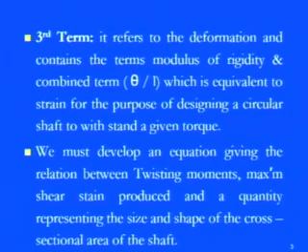So generally, if you remember the previous case, we found that AB was the length in the circular bar. Whenever there is no loading condition, all those layers are well set up within this circular bar. But as we apply the torque, B was shifted to B dash, and that shifting was at the extreme corner, whereas A was exactly at the same point even after the loading.